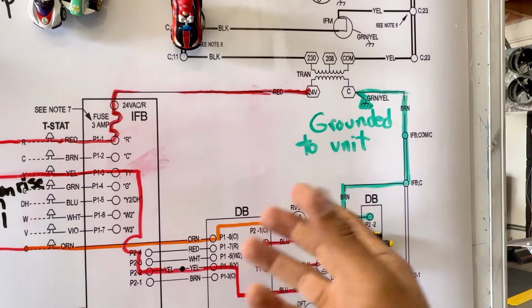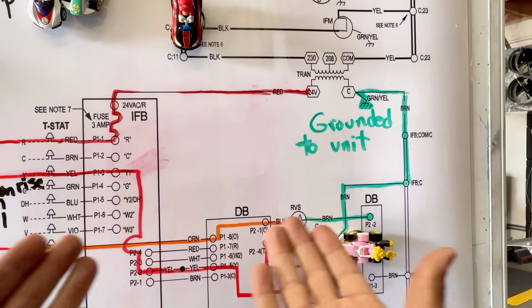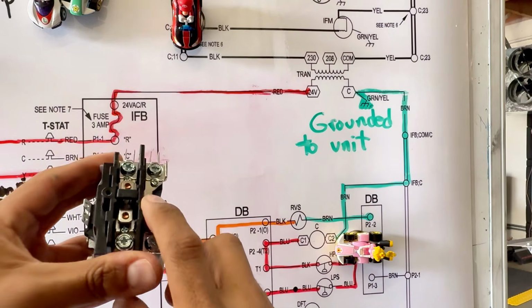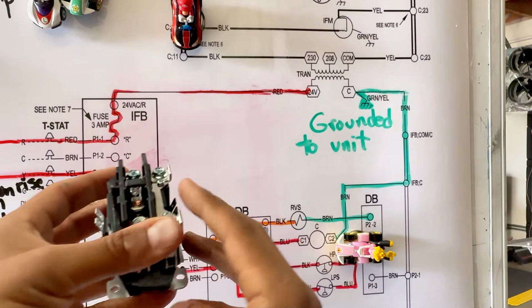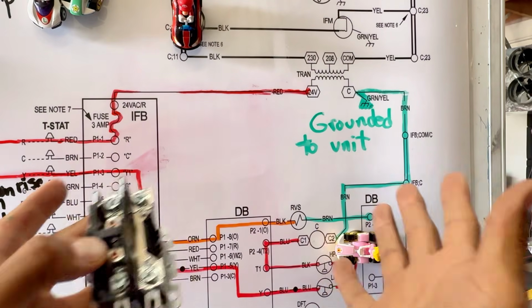They need to be there, and once they work it out, they'll be able to work together, and that current will make that contactor pull in, boom, and then turn on the compressor. High voltage goes through, because we're not messing with the high voltage. It's already wired for you.